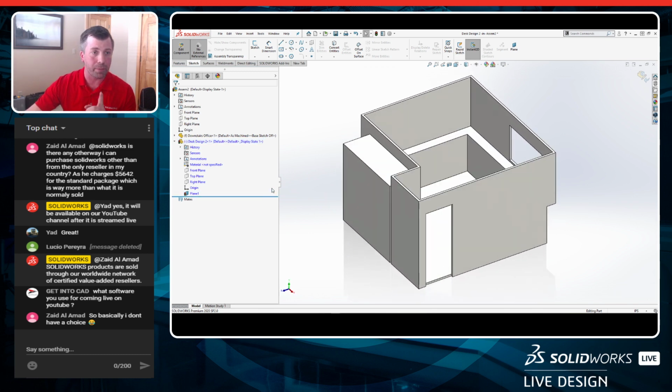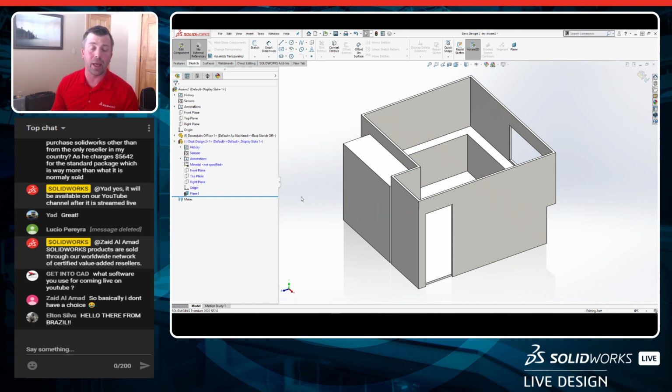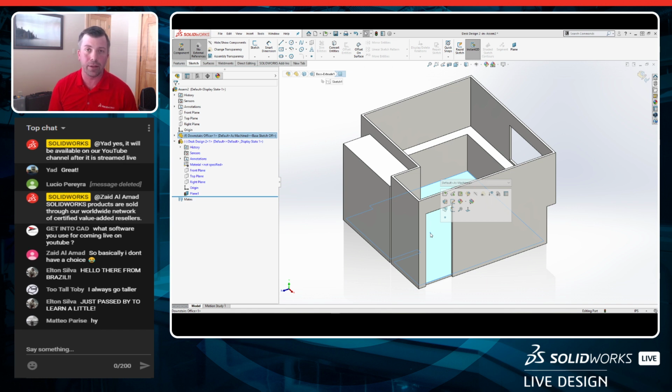Now let me go back because I missed something, and I wanted to point this out. Now I'm working in context of the assembly, meaning that I can reference other features of the assembly building this design. As I do that, whether it's a sketch or, in that case, I created a plane, it's off of the top plane of that part. But if I did it off another plane or even selected on here, that creates an active reference, meaning my new part, the desk design, is looking at the office space to be able to figure out where that location is. And this can be great, or again, this can be not so great. It really depends on the design intent that you have as a designer engineer.